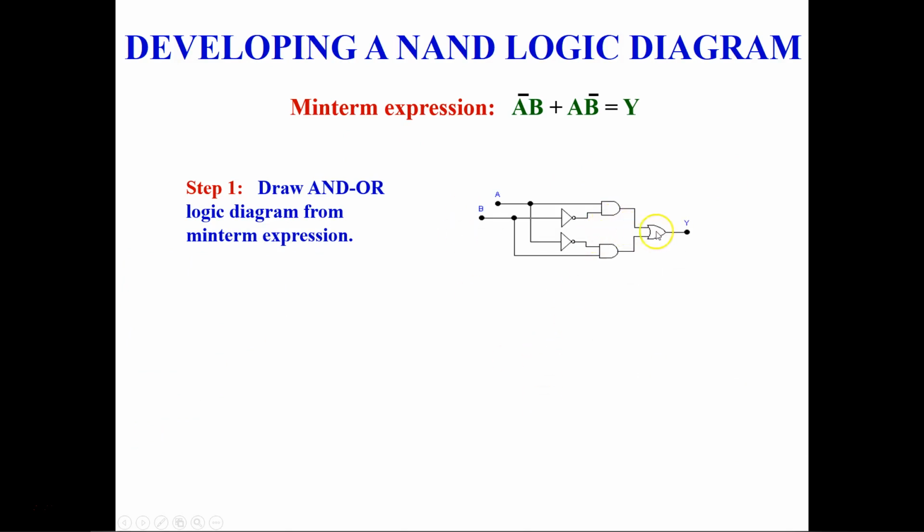So you saw this is our OR gate, which has A bar B and A B bar, and that is equal to your Y. So these are the two AND gates. So A is going in here, and then B is here. Okay, so some part of A is going into this AND gate, but this A is complemented.